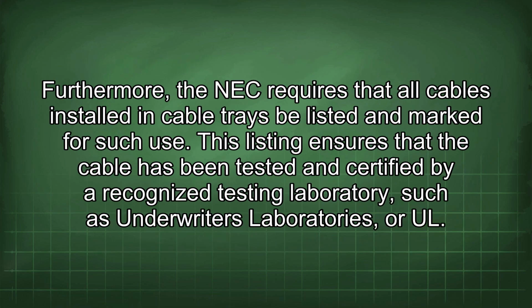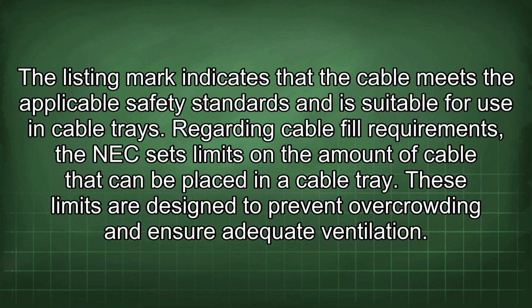Furthermore, the NEC requires that all cables installed in cable trays be listed and marked for such use. This listing ensures that the cable has been tested and certified by a recognized testing laboratory such as Underwriters Laboratories, or UL. The listing mark indicates that the cable meets the applicable safety standards and is suitable for use in cable trays.